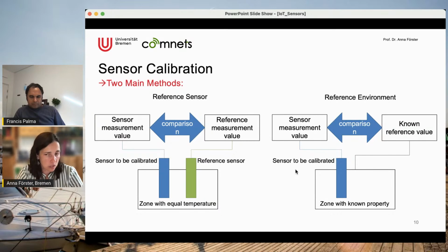And again, the same story starts, whether it's linear or non-linear, how many measurements you need in order to get your calibration line. This is very important because you will notice very often, especially with a little bit more complex sensors like volumetric water content, or a salinity sensor for water, or a pH sensor for soil or for water, they need to be carefully calibrated and regularly recalibrated. All is specified by the manufacturer in the specification sheet, but you need to know that it exists and that you need to take care about that.